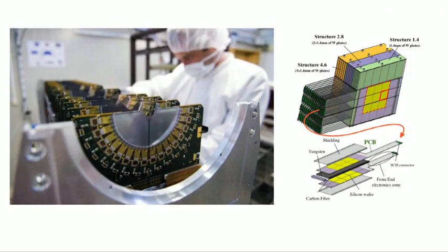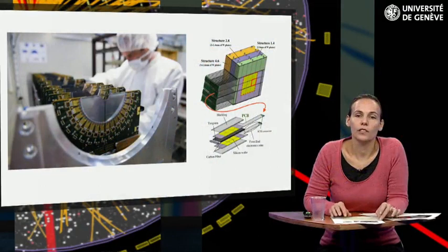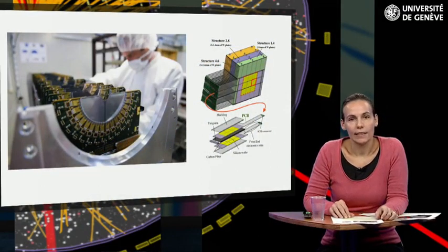Applications of semiconductor detectors in particle physics include the following. They are used arranged in layers to measure the trajectory of charged particles, and this profits from the development in microelectronic technology to fabricate precise structures on silicon and other semiconductor materials. Examples are microstrip detectors used in ATLAS at the Large Hadron Collider and in AMS, pixel detectors, which have been used for the first time at LHC, charge-coupled devices, CCD, used in digital cameras, and many others.